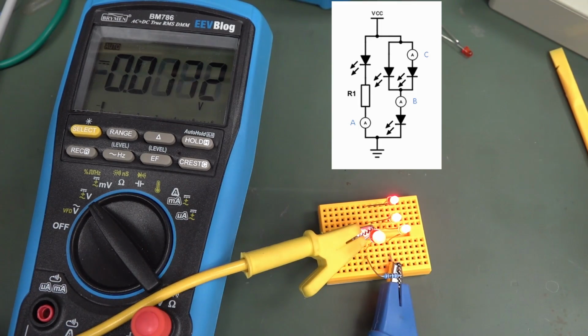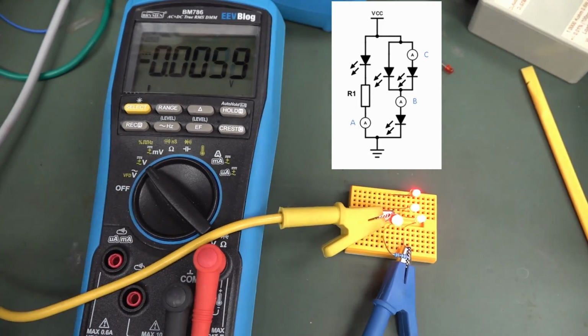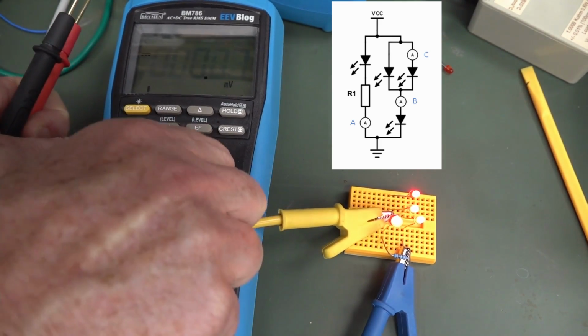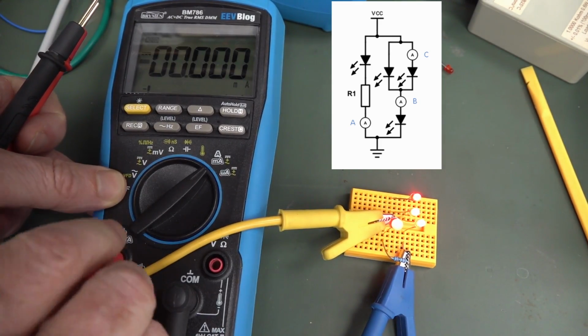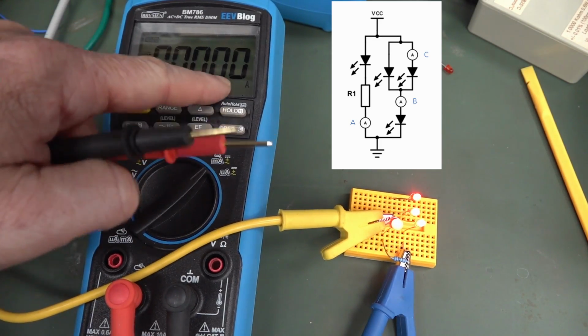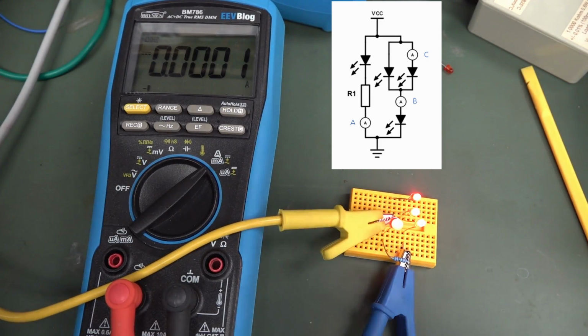How much current's actually flowing down there? Well, we'll have to measure that. Now, of course, burden voltage of your multimeter could get in the way at microcurrent levels, but I couldn't be bothered. So I'll just whack it on the amps range and put it on the amps jack here, and that will give us a 0.1 milliamps resolution, but really quite low burden voltage, okay?